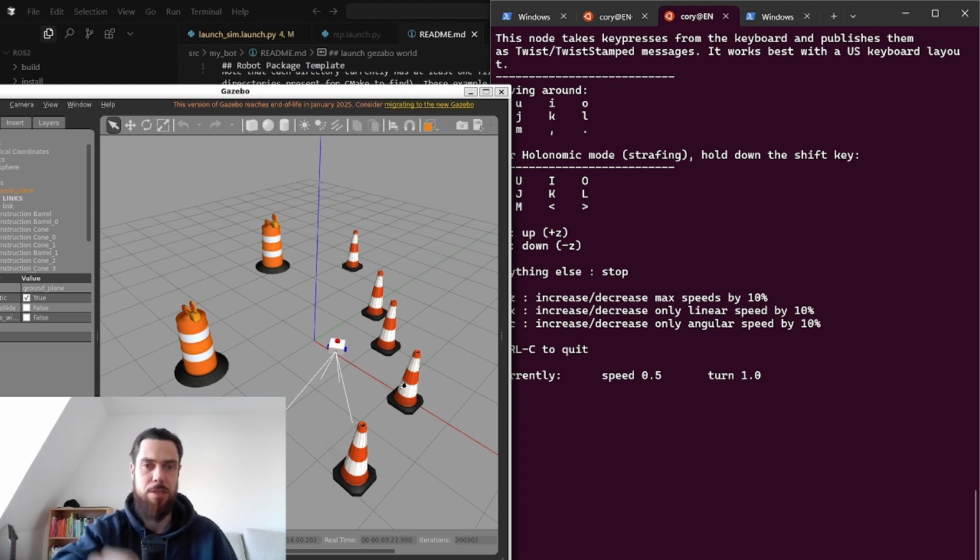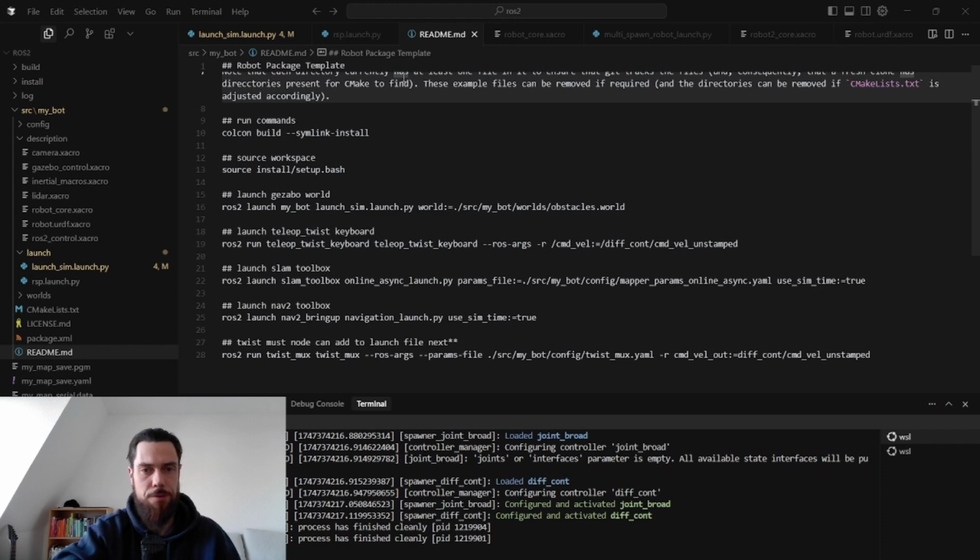It has to drive around using the LiDAR, creates a map, and memorizes it, and then can create a path through low-cost zones away from the obstacles. Then you pick the direction and the pose, and it'll drive there. I'll get that set up for the next take.